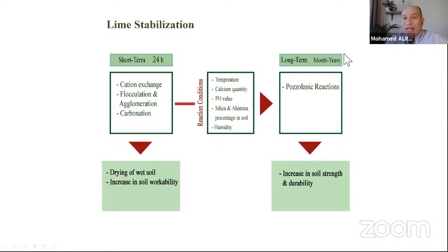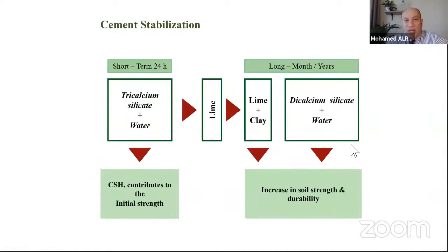It is the pozzolanic reaction, and this reaction results in a sophisticated formula of calcium aluminate silicate hydrate. This is a type of crystal which is very strong, by the way, and this is the element responsible for increasing the soil strength, durability, and water resistance at the same time.